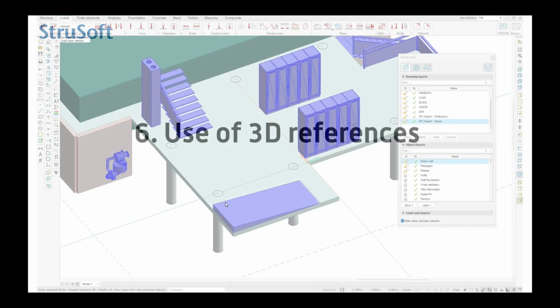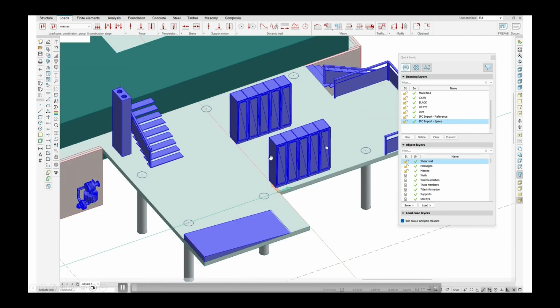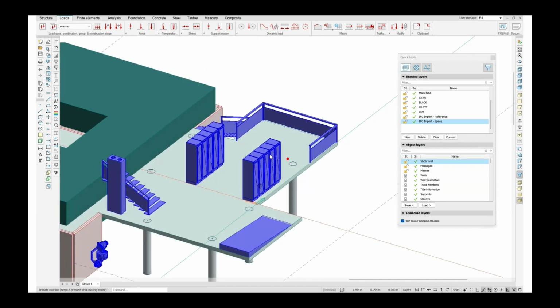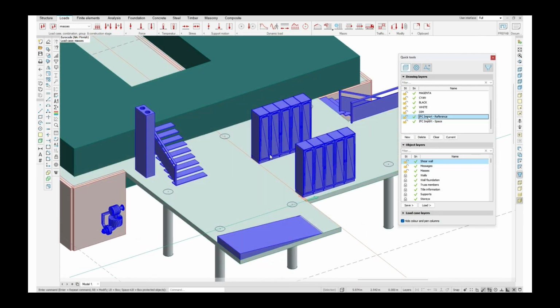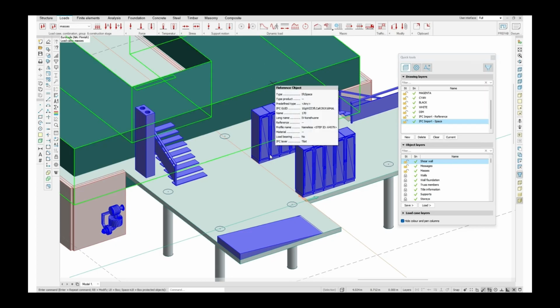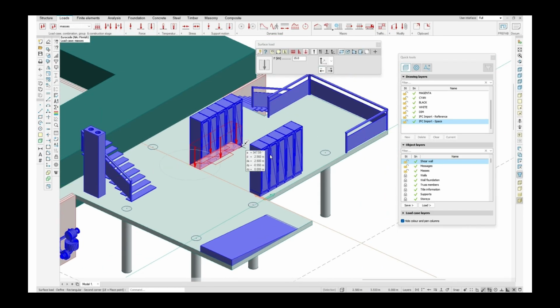Any other uses of 3D references? We can also make loads with the 3D objects that we can input as a solid. So if you have a plate like here and you want to define loads really quickly, you can input your references, and I can also input IFC spaces here. Now if I define the loads, I go to surface load and I set the resultant of an area. I can really quickly define loads on my 3D model by importing those objects which will cause the load. They can be these railings here, IFC railing.